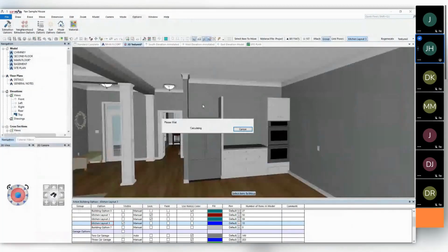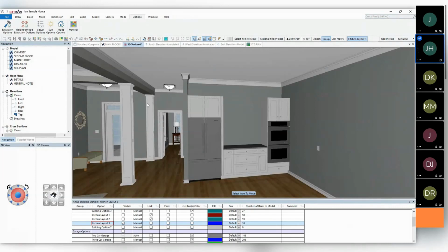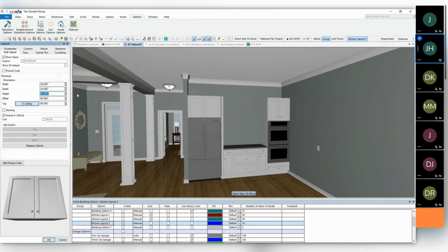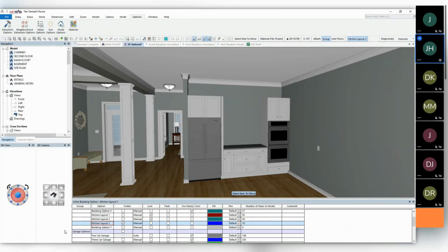Now, as I take a look at this inside 3D, okay, it will, again, update the model here, and I'll be able to see where that cabinet is in terms of its height. And obviously it's too tall because I've got this in here. Now I can just simply do an edit from here and change the height, or I can even use the adjust feature like I did when I stretched the drawer cabinets to fit. And so once I've edited this cabinet, here I can see the height, and I could now just come in and key that in at, let's say, 24 inches. Okay, it keeps the same measurement to top of ceiling. And then as I click OK, it's going to recalculate that and rebuild that for me.